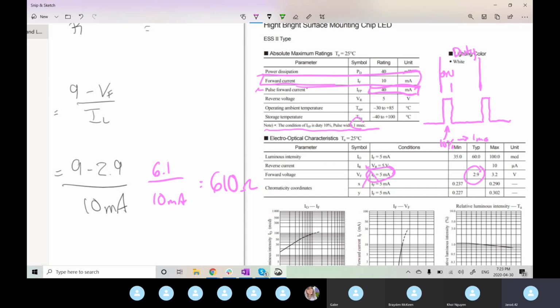But that's primarily just saying only for a short period of time, which would generally be during startup, that you would see a possible higher spike of 40 milliamps, based on the ringing effect that we've seen before in any square wave, that it'll overshoot. So that's just saying it's tolerant to allow some peak for a short duration.